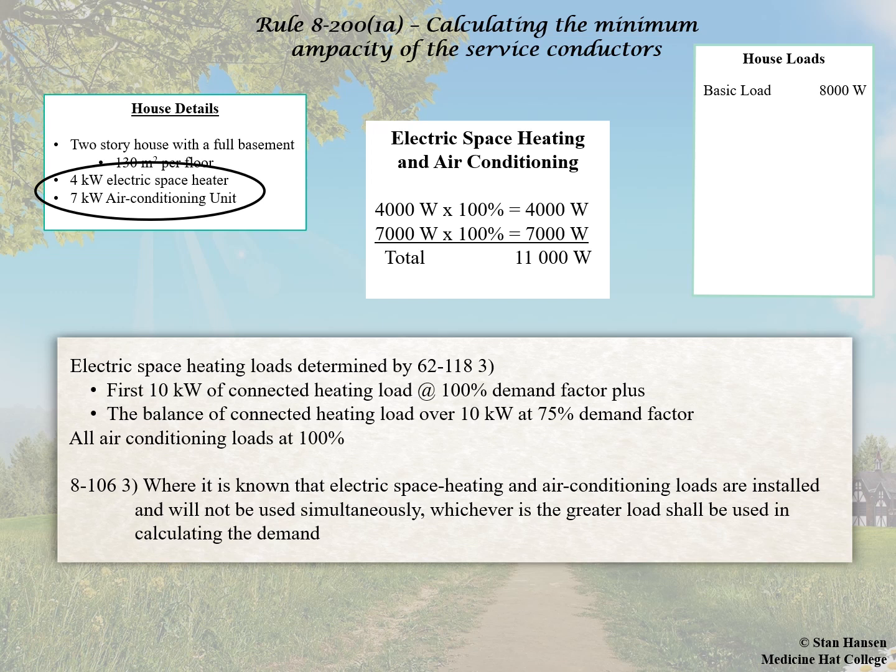When it comes to our service here, we're going to take the 4,000 watts for our heating, add it to our 7,000 watts for our air conditioning. We get a total of 11,000 watts, and we're going to put that load up on our list.